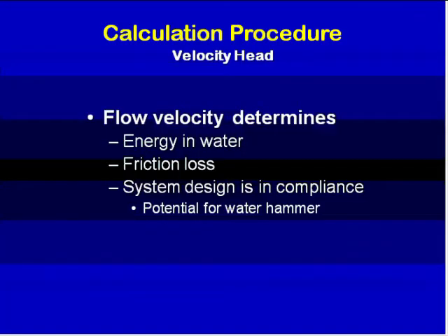So why are we interested in the velocity head? Well, the flow velocity determines the energy that's in the water that we've just discussed. As I mentioned, it's going to help us in determining what the friction losses are going to be. And lastly, and to some degree maybe the most important part of this whole thing, is that we have system design and compliance kinds of things where we want to minimize, if not eliminate, the potential for water hammer in the